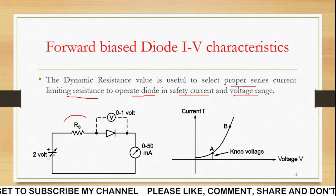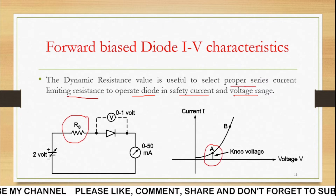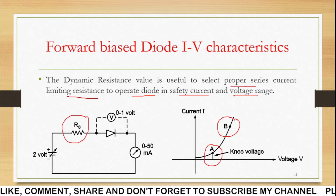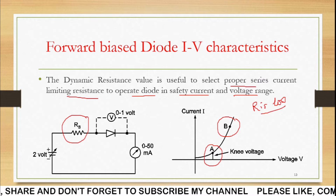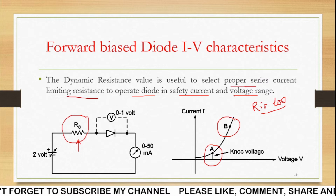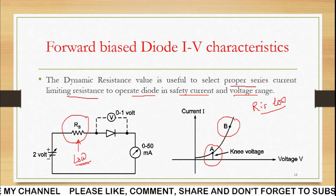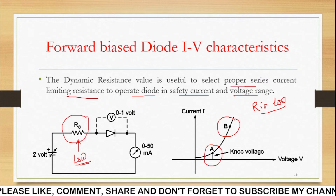So we can see here this resistance Rs will be selected according to these two resistances, at A and at B. By just seeing that particular slide, you have seen that the resistance is very low. So we don't need to take the resistance Rs to have a very high value; the resistance Rs should be very low. So let's look at how the simulation of the circuit is drawn in the PSpice software.